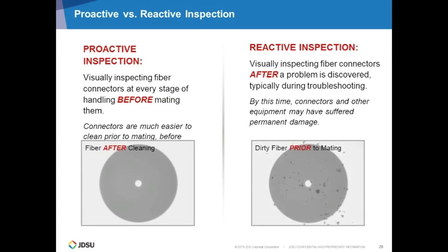After you connect the fiber and there is dirt, imagine the dirt like a rock, while fiber is made out of glass. It's a huge pressure where the 2 connectors are connecting. It will basically create damage on that interface. So if you plug in the fiber and it is not working, then you unplug it and try to clean it.